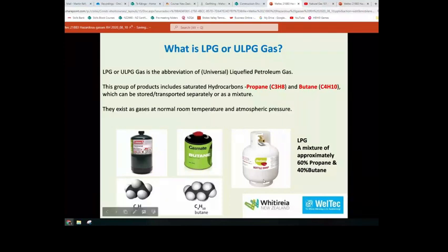So a lot of requirements around LPG bottle installation are due to the fact that it's heavier than air. So if it did leak out, you wouldn't want it going underneath your house, where if it ignited, it could blow it up or cause a major fire. Whereas if it was natural gas, it's likely just to dissipate off into the atmosphere.